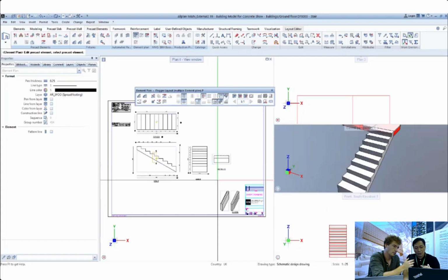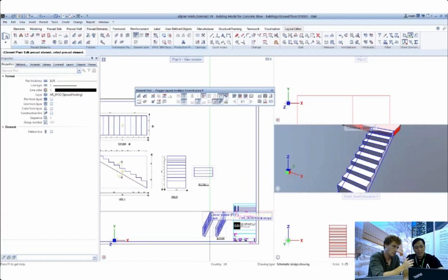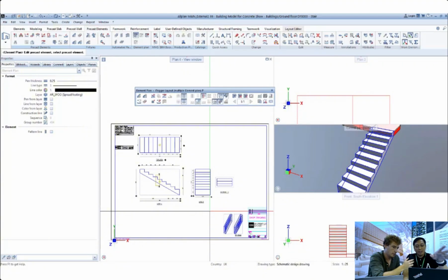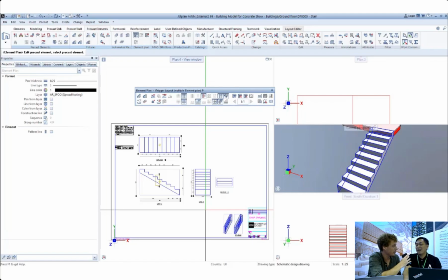So basically, as I mentioned to you, it depends on the orientation that you have defined. Okay. Yeah. So basically, the 3D model is not quite right. Maybe we can try to find a suitable one so that everything will be complete. But this is all automatic. I don't have to draw anything. Exactly. That's the one point. So we just click on the selected layout, and then you have already the element. So the only difficult part is the orientation, and apart from that, everything is auto-generated. Exactly, that's the point. So that's how Allplan Precast can give you the fastest way of creating shop drawings.